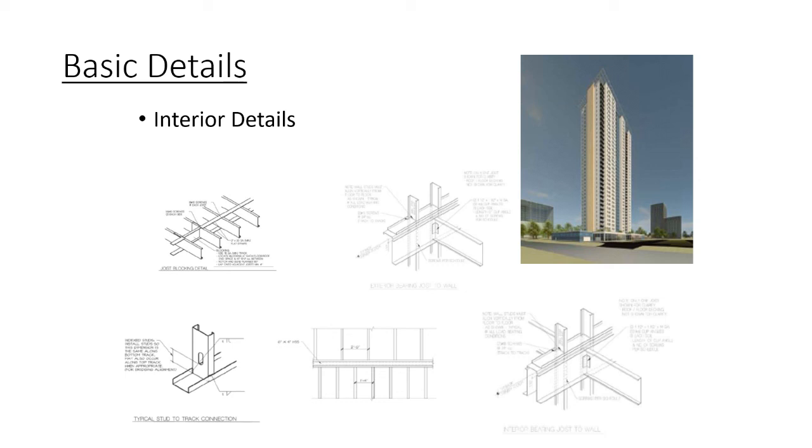Going to the lower row and furthest to the left, the designer has opted to use welding to attach the cold-formed steel studs to the bottom track. The designer could have opted to use mechanical fasteners such as screws, but in this case chose welding. The point to be made here is that that is an option from a design standpoint, either to weld or mechanically attach stud to framing.